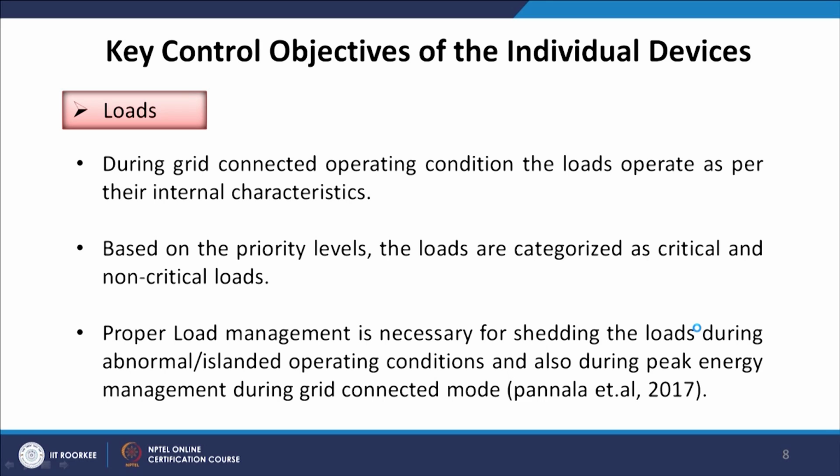Now, in the evening, let us say it is a PV connected islanded DC microgrid. During evening times when the load is more, I do not have PV, so I have to discharge my battery. But the storage cannot be discharged below 10% of SOC, which is very expensive and the battery life may go down. So, under those circumstances, I have to very carefully curtail my loads based on their importance, whether they are critical or non-critical, to match the generation available to me and the loads.